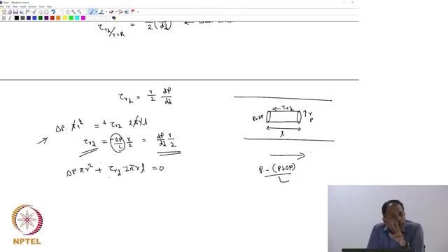Depending upon whether you want to talk about the fluid element exerting shear stress on the fluid outside, or the other way around, there exists one convention. There also exists another convention in which you interpret shear stress as a force or as momentum flux. So, the minus is essentially to do with that. But the point is that when you consider a fluid element, pressure is the one which is going to push the fluid to the right side, shear stress is the one which is going to push the fluid the other way, and it's a balance of that.